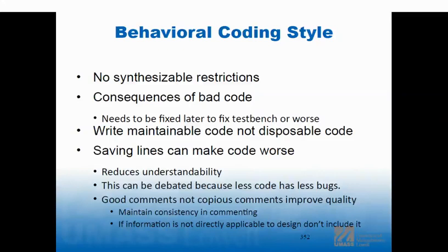So, to pick things, we might create very complicated memory structures in the scoreboard, right? So in the test bench, we might create very complicated memory structures. Well, very complicated memory structures have problems if you don't design them carefully, right? You overlap things, you overrun the records next to other records. And if you don't have that nice sharp structure that you would have in the RTL, you can run into problems. And the problems are maybe even hard to find because I know me and I do more design than verification, but I do a fair amount of verification. When something is wrong, what do I think is wrong?